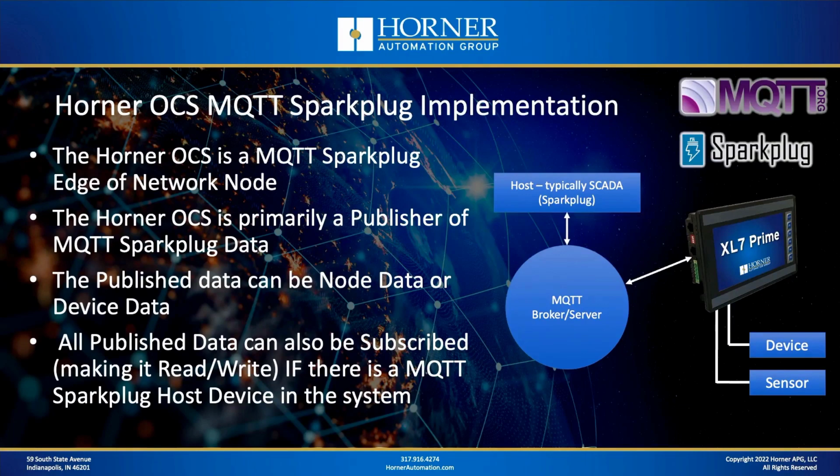Well, if there's a Sparkplug host in the system, that Sparkplug host can automatically see all the data that the OCS has published by effectively browsing the tags over MQTT. And it also now can write back down to the OCS any data that the OCS allows to be written, including something like the set point for a well, for instance. So one of the key roles that the host does play in a Sparkplug system is turning published-only data into published-subscribed data.